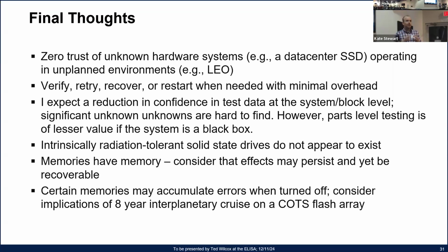It's normally a non-destructive SEE, but because of the way that it affects the system, it now can't find any of the data that's been mapped all over the drive, and it fails in a truly destructive way from a mission standpoint, even though it's not a destructive SEE that people like me would have thought of from a physical standpoint. And so communicating that to systems developers is very challenging: it's not just the destructive SEE. In fact, that may be prevalent, but not the driving risk. It may be the way the errors are handled by the system.